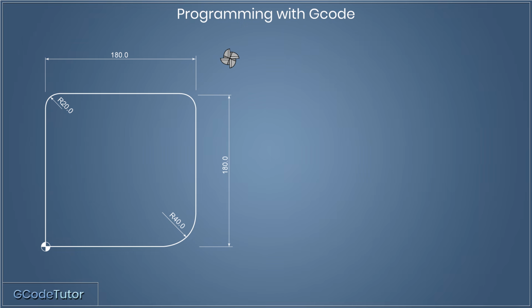So let's have a look at the first line of every program. Now the first thing the machine sees is the program number. Now this is in brackets, which means the machine doesn't actually read this. Things enclosed in brackets are operator's notes. It's not read by the machine. The machine knows which program this is by the file name that we call it. So I've called this program 2001, and at the end of this line we have a semicolon. This means end of block. This tells the machine this line is at its end. So after every line of G code we add an end of block code or a semicolon.